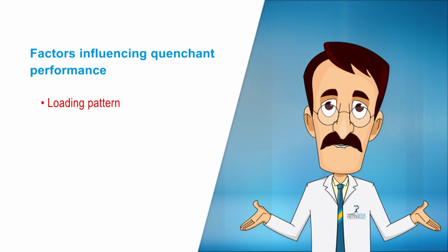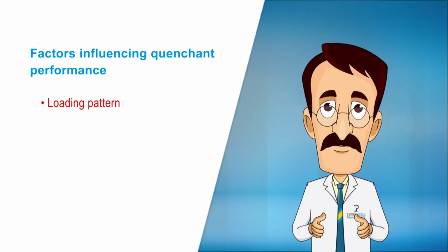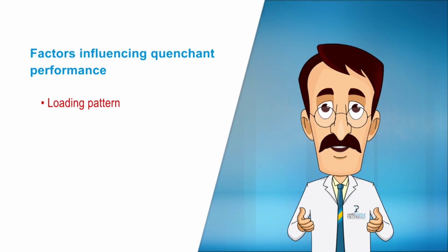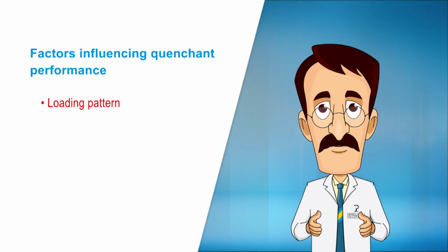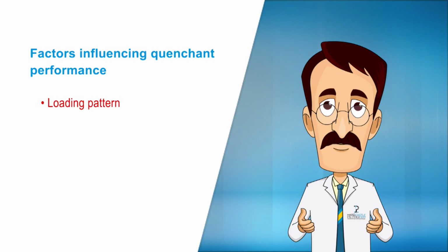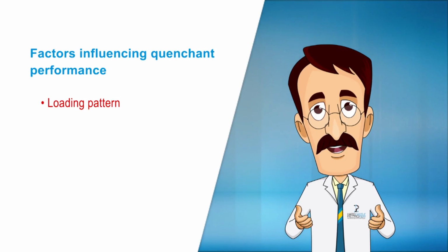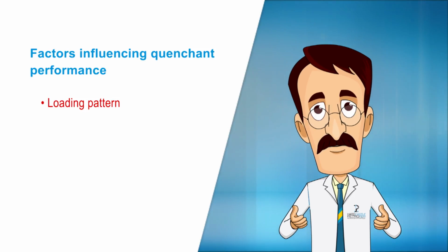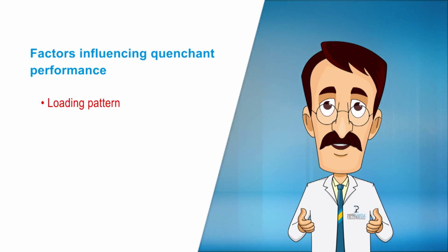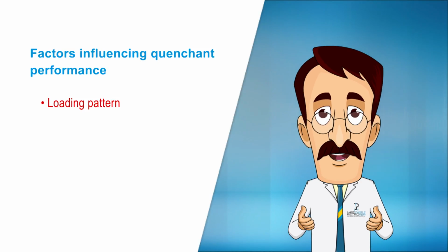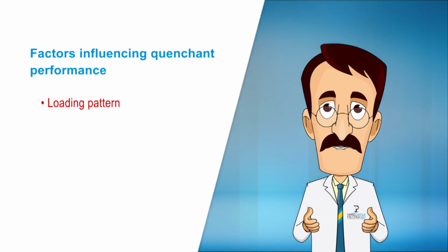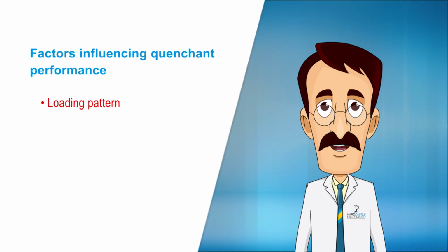Now we see the effect of loading pattern. This relationship depends upon the conditions of the use of the oil and upon the size of the components. Larger components which take longer to cool cause a lower thermal loading to the oil bath than tightly packed batches of small components which give off their heat rapidly.